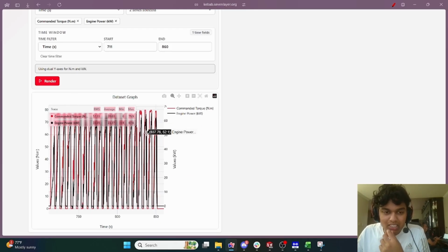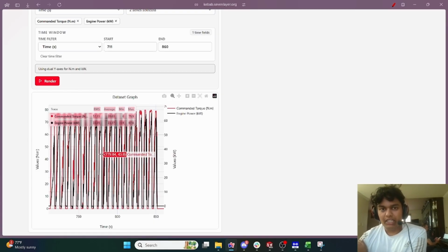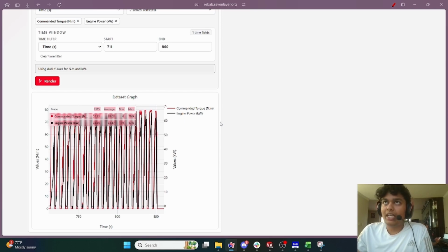When we did this drive day, we power limited it, but it probably matches what endurance is. What power limiting is: we can run a maximum of 80 kilowatts, so at one point in time we can only push 80 kilowatts, but we power limit. So you say, hey, you can't exceed 30 kilowatts of power, you can't exceed 20 kilowatts of power, because during endurance, which is around 28 minutes or 22 miles, we don't have the capacity to run at 80 kilowatts for 30 minutes.